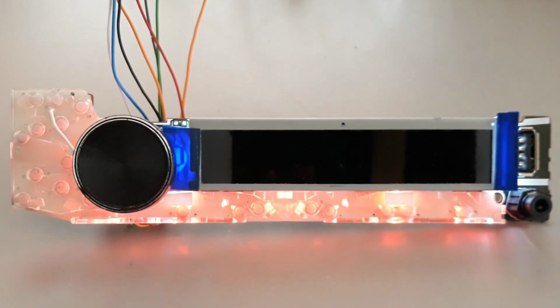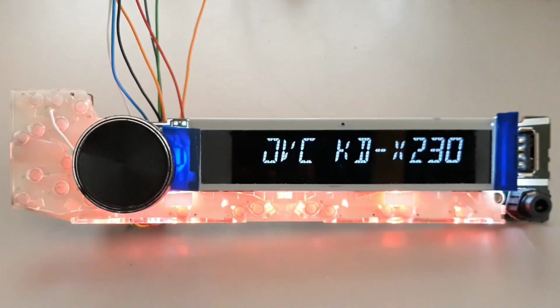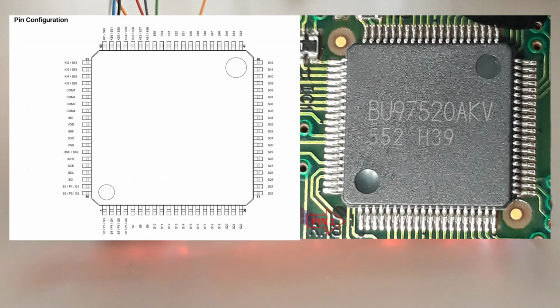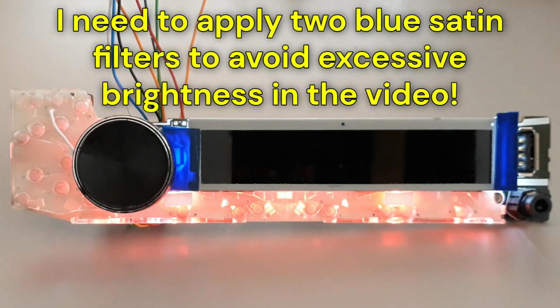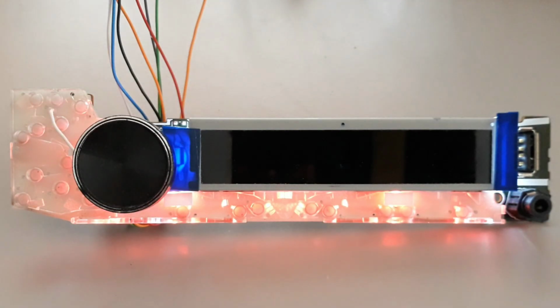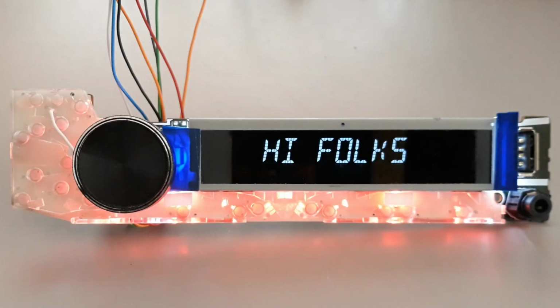Hi folks, today we are adding another LCD driver to our collection. This time, the driver comes from ROM Semiconductor with the reference BU97520AKV. This driver supports 4 command lines, or 4 COM lines, with 69 segments on each one. That gives us the ability to control up to 276 segments.